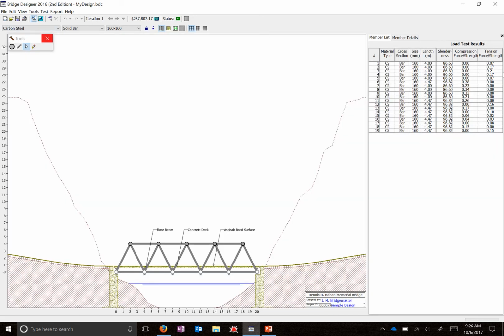and you'll see over here on the right hand side these numbers. So 0 point what have you, okay? Our goal is to be able to design a bridge that still holds up but is as cheap as possible. So we want these numbers to be as close to 0.9 as possible. So what we need to do is come over here, make sure we're on the tool, the selector. We're going to click up above to the left of the bridge and drag the box so we select all of the pieces. You'll know that because it'll turn blue here and it'll all be blue here.